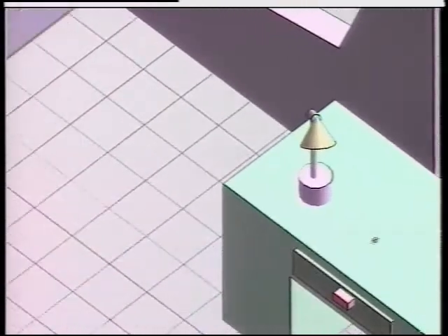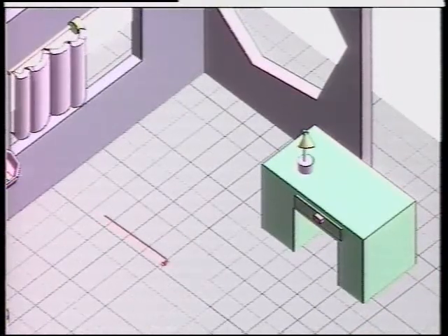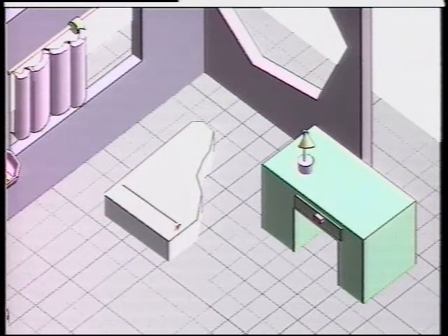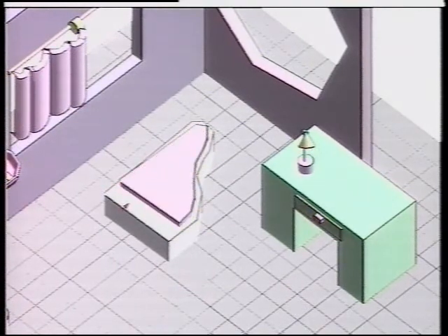To construct a piano with a raised lid, we again use both the CSG subtraction operation and rotation constraints. In this sketch, although we want the piano lid to be lifted, it is much more difficult to draw shapes at arbitrary angles. Instead, we draw the lid initially on an axis-aligned plane in the closed position. This allows us to use the piano base as a guide. To raise the lid, we draw a rotation axis that serves as a hinge, and then drag the lid to the desired position.